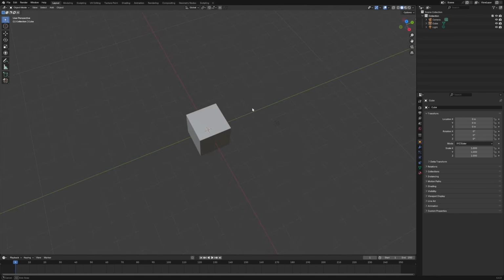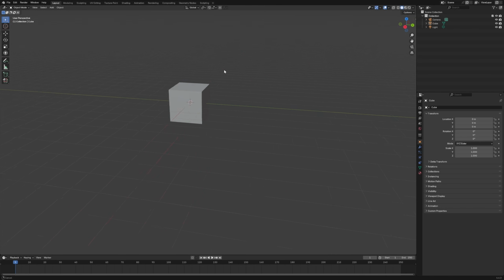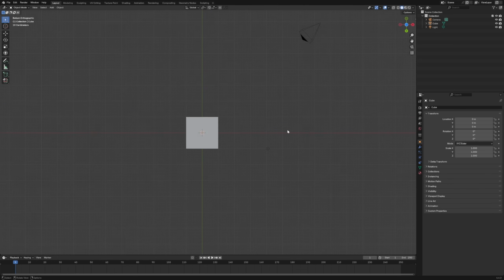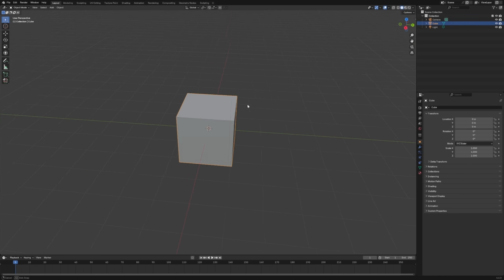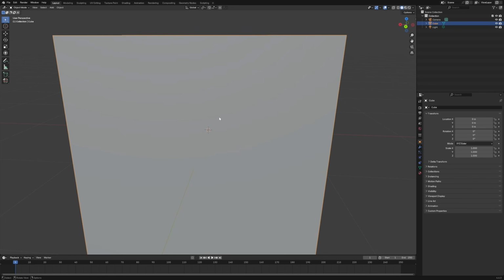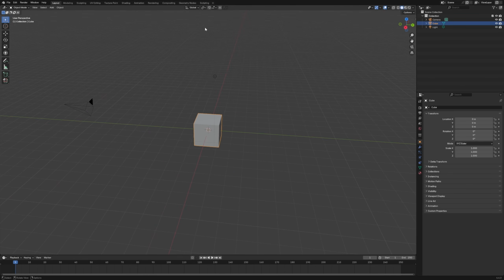So for Blender, you have all these objects and stuff in the scene. If you use the middle mouse button, you can move and rotate around the camera. If you hold shift and middle mouse button, you can then move around the actual camera as well. I use a full keyboard, which is really important for Blender. You can use the number keys to move camera things around or click the buttons here. So 7, 8, 9, all these different things move it around and keep the camera placed. You push 0, you go through the camera view, which is very helpful. If you click the shape and push period, it zooms you in. Awesome. These are the general things you want to know before moving around the system.